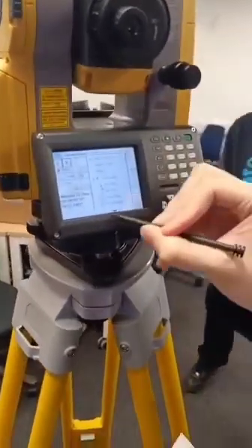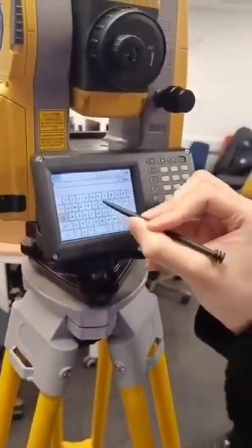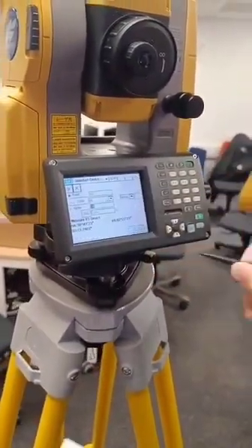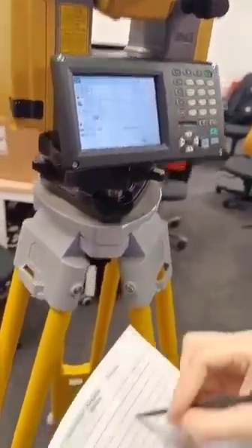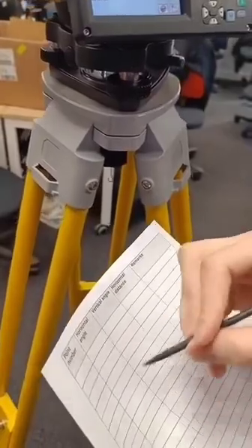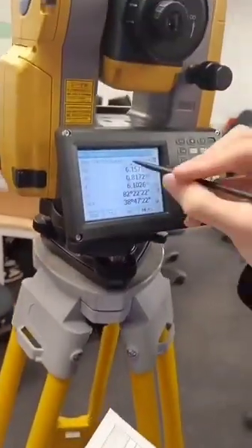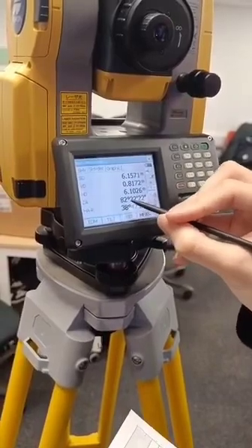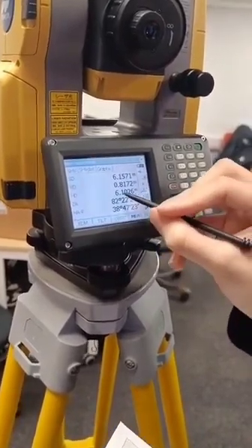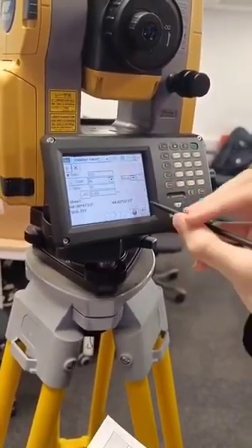And I'm just going to change this back to rectangle, change this to top right, so TR, just a quick abbreviation, hit measure. While it's measuring, just write your quick notes like point number, remarks, whatever, and you hop into here, take your measurements, horizontal angle, boom, vertical angle, there it is, horizontal distance, there it is. Then you just hit save.